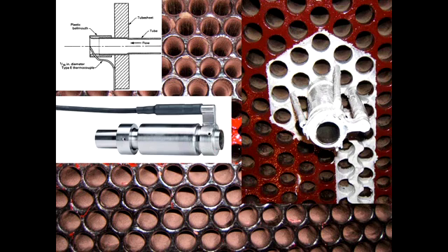Now it's attached to the tubes using the same epoxies that are used to coat water boxes and tube sheets. Both of the tube sheets shown in this diagram, this coating here actually has scale deposited on it. This black color indicates that it's a calcium and manganese containing scale. And then here's another tube sheet with a clean coating of plastic-core material, an epoxy that's used to commonly coat tube sheets. We use that same material to attach meters to tube sheets and coat the cables.